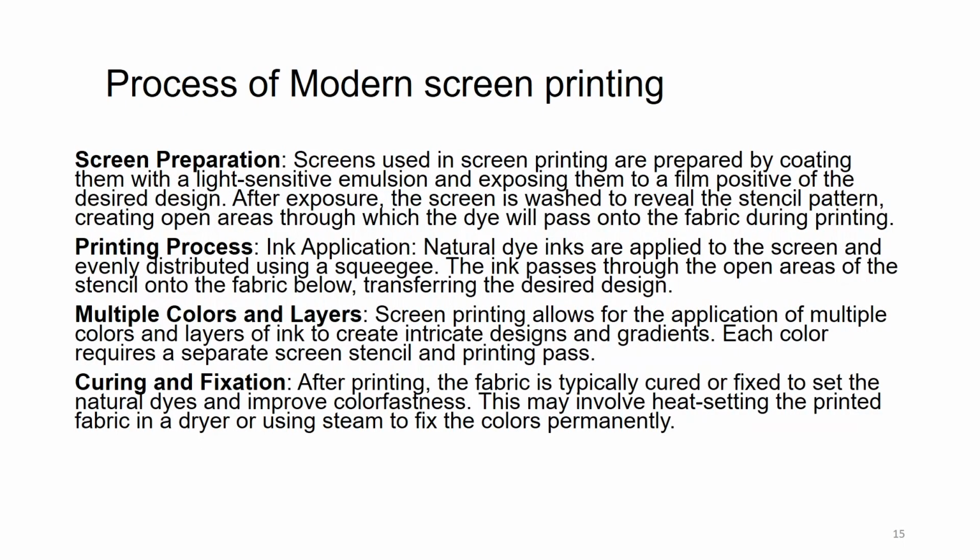Curing and fixation. After printing, the fabric is typically cured and fixed to set the natural dyes and improve color fastness. This may involve heat setting the printed fabric in a dryer or using steam to fix the colors permanently.